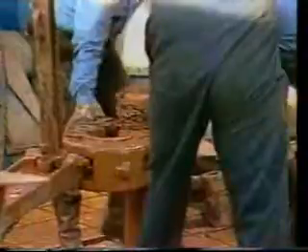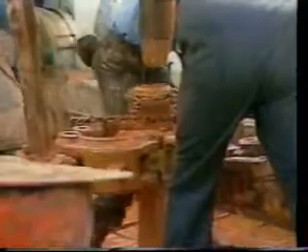Next, the Kelly is swung over to the pipe waiting in the mouse hole, and its pin is stabbed into the box and tightened up. The driller can now pick up the new joint and swing it over the pipe waiting in the slips. Here it is connected, once again using the tongs to tighten this time instead of loosen.